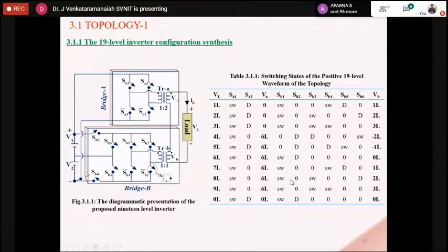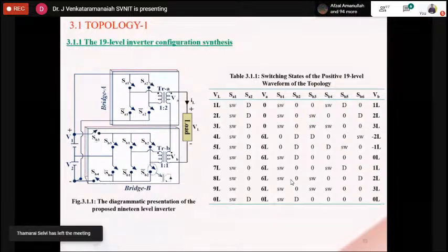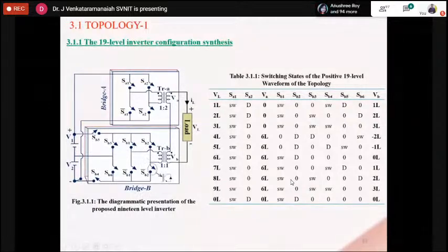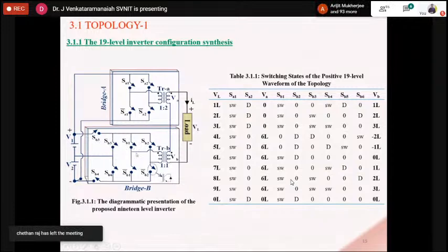For positive, we have to turn on SB1 and SB2 bar, and they will give the positive level, and then the other switches operate V1. So the current goes through SB3, SB1, reaches the primary winding of the transformer, then SB2 bar, and returns through SB6 for V1.